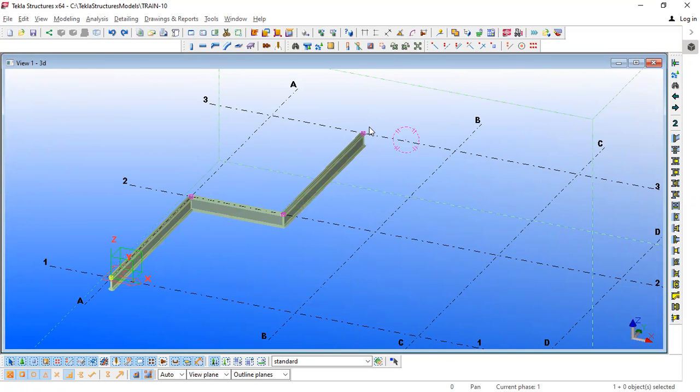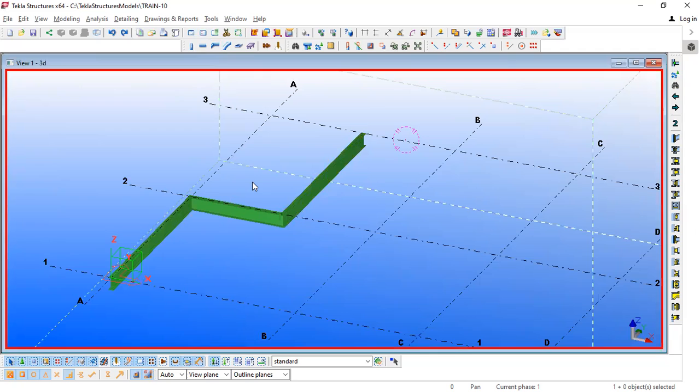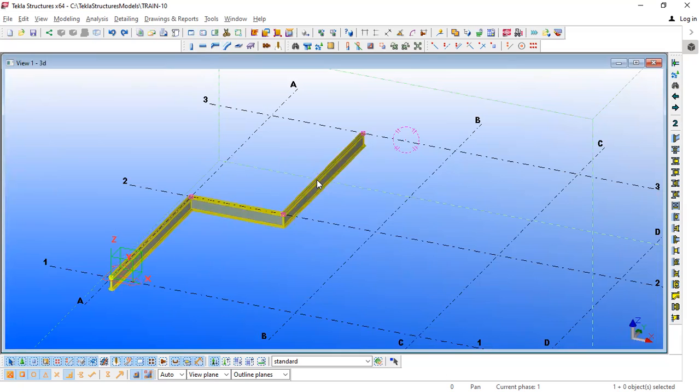If you have done AutoCAD, when the lines are continuous and you select a single line, it shows as a continuous line, even when it goes in different directions. Then it is called a polyline. So what is a polyline actually? It is made of different segments. Similarly, a polybeam is also made out of different segments of a beam. These are the segments of a beam. So that's why we call it a polybeam, right?